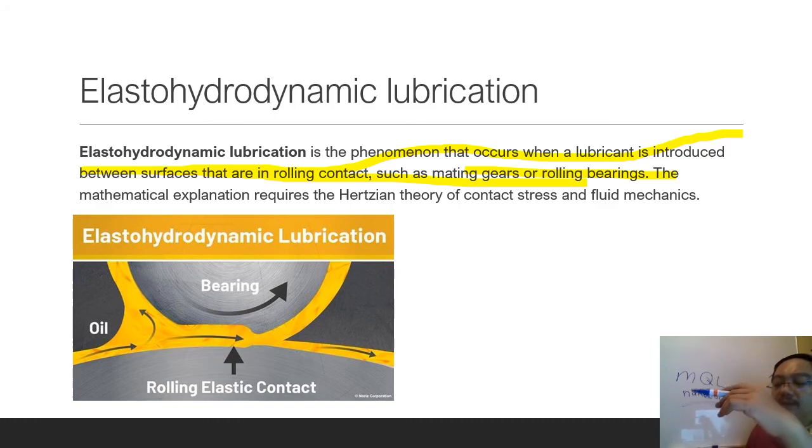Okay, for low velocity application, because at high velocity the grease may dissipate into the thin air. Because of high temperature, it will dissipate. It will make the grease disappear into the air. But alternatively, if the rolling contact bearing application is for high speed, you should use oil.